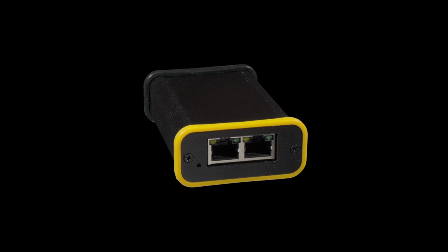A small note about the E1 interface is that we don't use a real E1 LIU, or line interface unit, and so we only officially support short-haul E1, which is fine for lab use or production use where the BTS is nearby for instance, but I wouldn't recommend trying to use it with multi-kilometer E1 links.